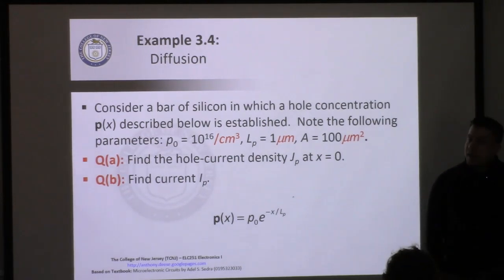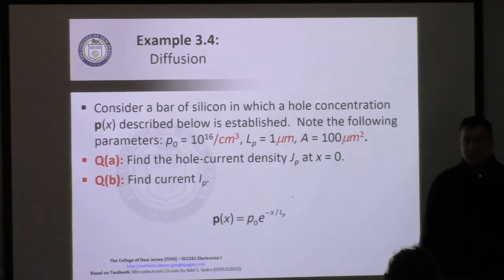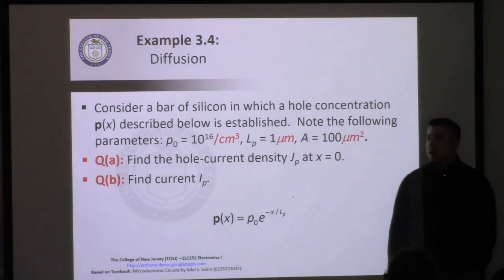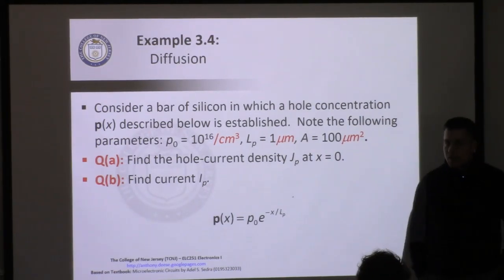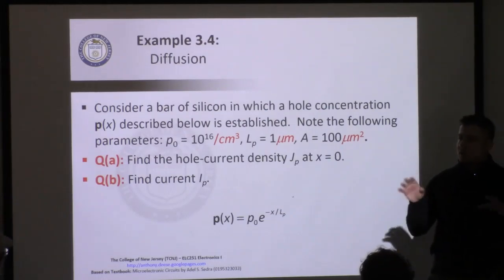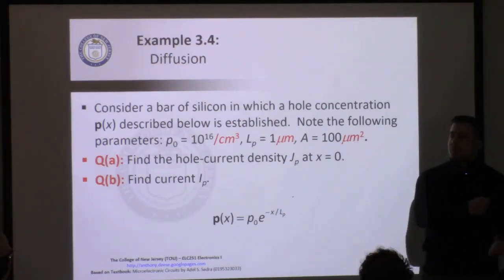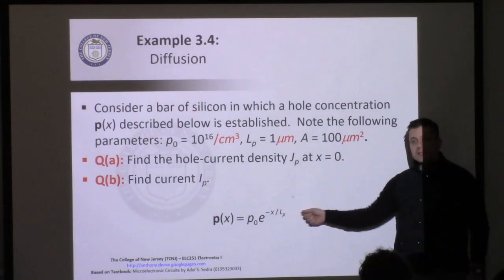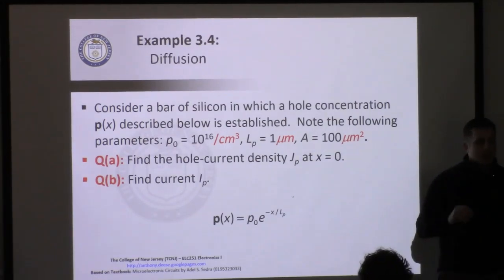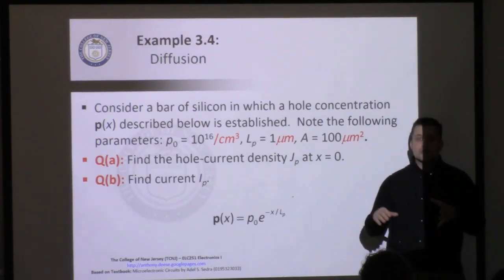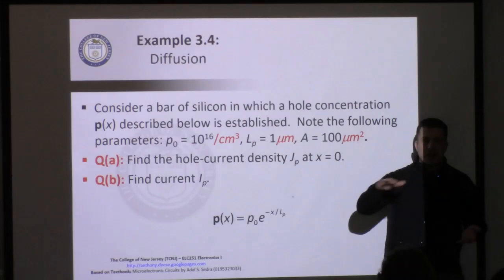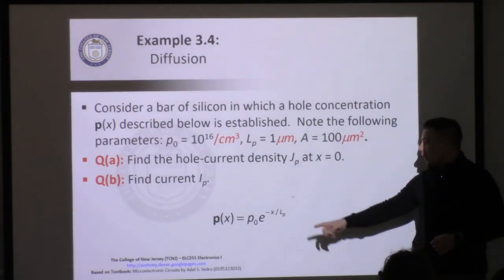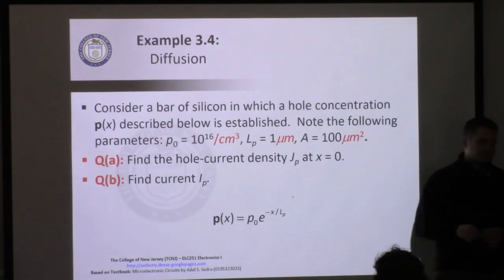Okay, so diffusion length, what does that describe? That describes how far this particle is likely to diffuse. Now that will change a little bit randomly depending on the exact circumstances and probability. But how far will this particle diffuse before either it recombines or the diffusion force drops below the force required to make it move, meaning that the gradient has flattened out enough? So how far is it likely to diffuse?